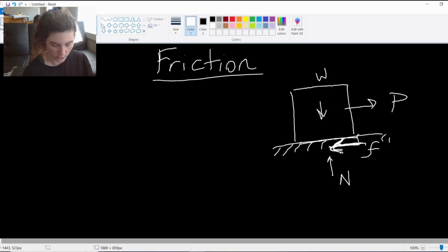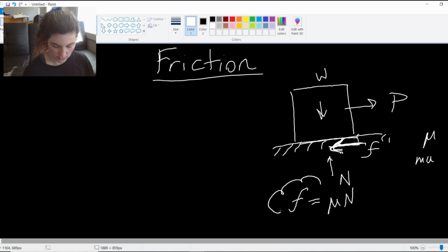So we've probably seen this equation in Physics 1 already, this friction F equals mu, the Greek symbol mu. Our frictional force, static or kinetic coefficients of friction, right? Mu is the coefficient of friction times the normal force. This is our friction equation that we've gotten used to seeing probably in physics, and we're going to be using it again here, but using some of our knowledge of statics to apply this equation.